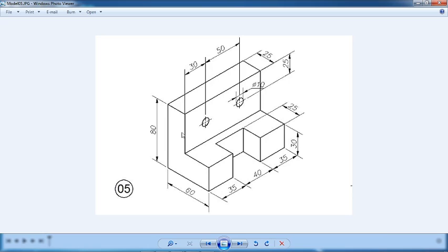So in this particular exercise, we are going to draw the L shape cross section on the front plane and extrude symmetrically to the total length. The distance is given as the summation of 35, 40 and 35. So what we will do is first create this shape, the C shape.